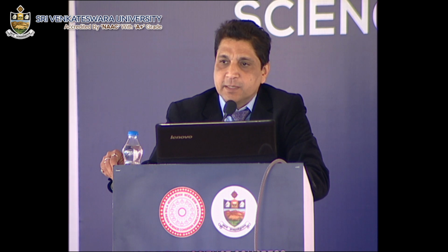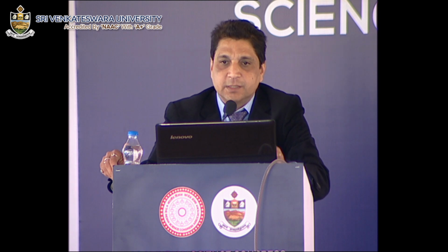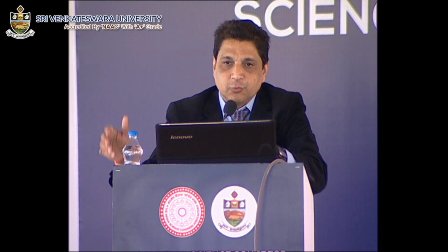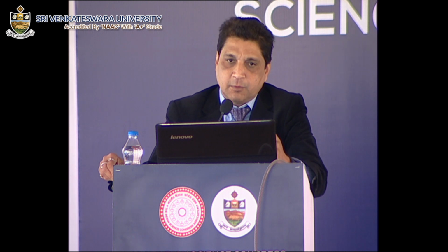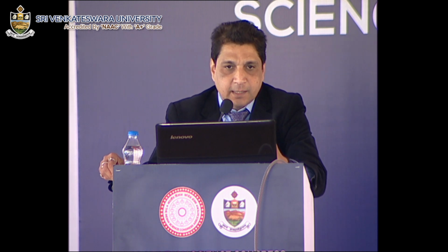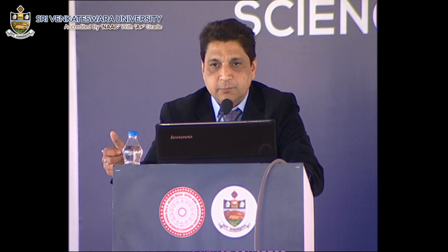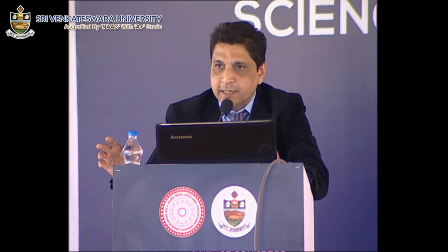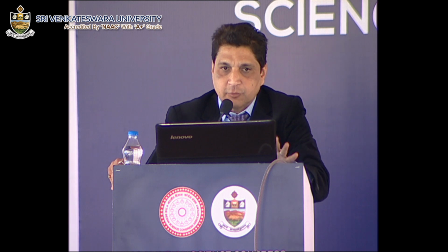And the second problem is that at the moment, near the coast, whether it is Ramanathapuram or the Gujarat coast, the substations which are available are not sufficient to evacuate the power which will be coming from offshore. We need to upscale the transformer capabilities and the three-phase transmission lines, and only then can we plan good DC cables by the shortest possible route to evacuate the power into the substations. So all that work the ministry is trying to plan, and we have formed a green energy corridor where they are looking into forming these transformers and upscaling this.